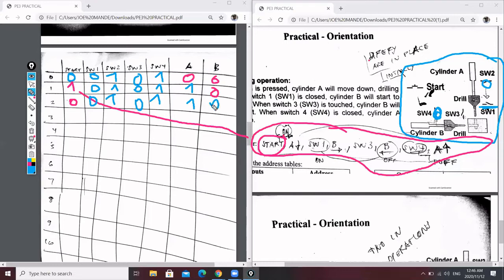And then on step 3, it says cylinder A start to drill. Remember you have a weight which was on top there. If it starts to drill, the weight will move away from that, and it can be somewhere in the middle here. So it's still drilling. The change that will occur is that switch 2, the switch that is up here, will open.